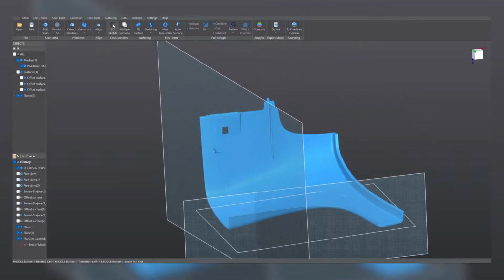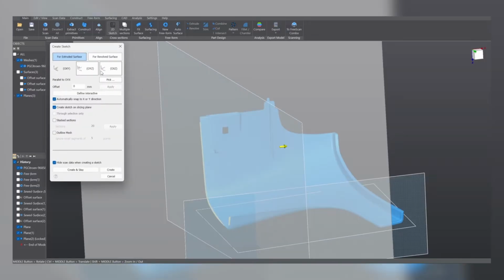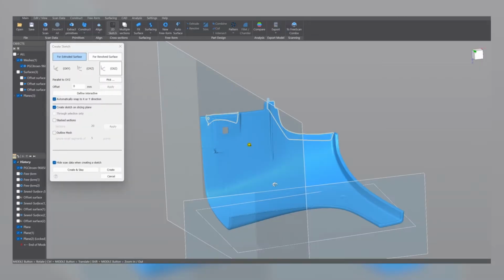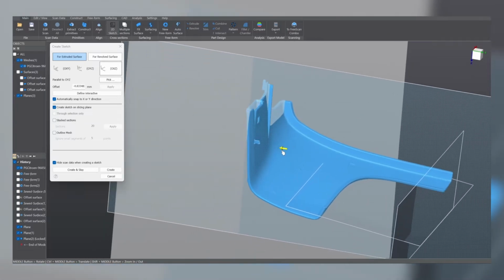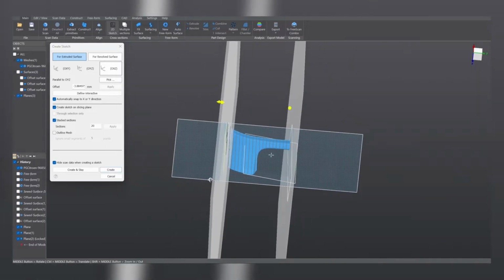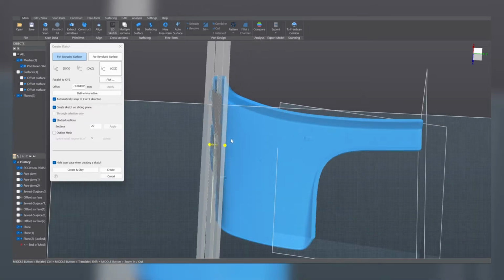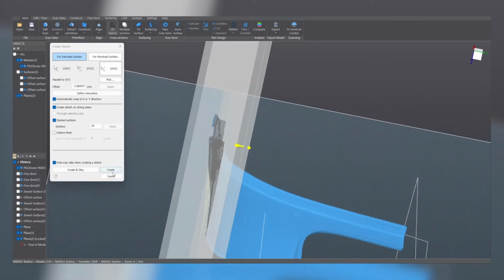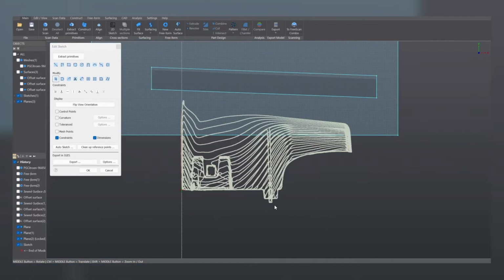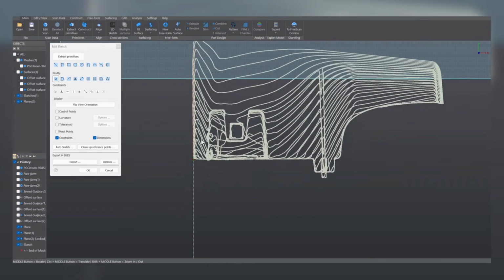Cool. Now, for this geometry here, the way to approach it is by extruding a sketch, an open sketch, to obtain a surface. So let's do it. Click on 2D sketch, select the proper orientation, and the first thing that we observe is that when moving this plane, we are not able to slice on the position that would work well for us to extract this information, right? So I'm going to show you a trick. Simply go to Stack Sections and move this volume until you compress all these 20 sections on the region of interest. So you have all the information here with a lot of density, and therefore you can clearly see the result that you were looking for.